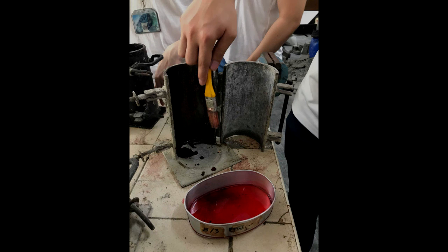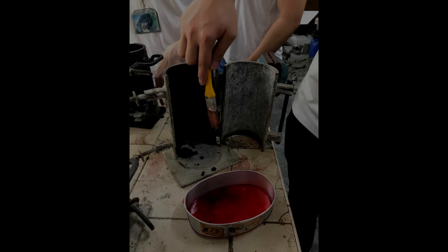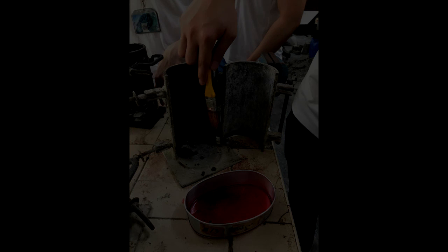Concrete is typically cured for 7 to 28 days depending on the property that will be tested. The longer it is submerged in the water bath, the stronger the concrete. This water bath will maximize the hydration of the cement in the concrete.